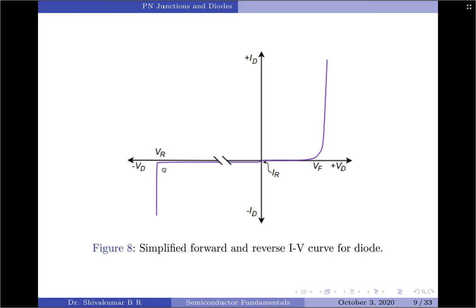There are two mechanisms behind this phenomenon. The first one is the Zener effect, named after Clarence Zener, which predominates when the doping levels are high and produces breakdown voltages below roughly 5 or 6 volts. It is due to the production of a very high electric field across the depletion region, which then results in a very high current through electron tunneling.